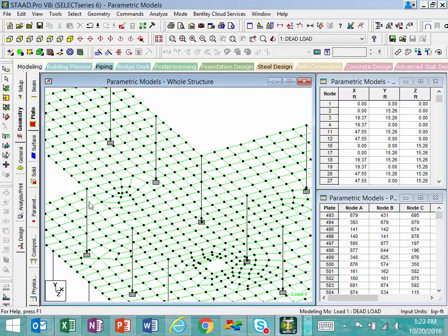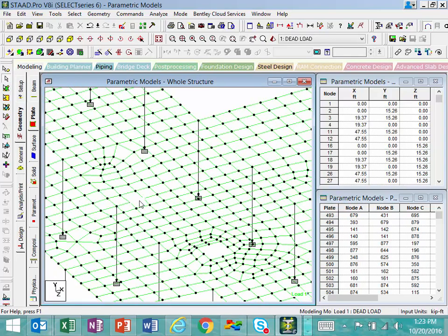I can also see these interior beams. Before, when this beam was modeled, it was modeled from column to column. In order to ensure proper force transfer and monolithic action between this slab and this beam, it's important for the beam to be segmented at the exact same location as the slab, which you can see was done automatically for me.